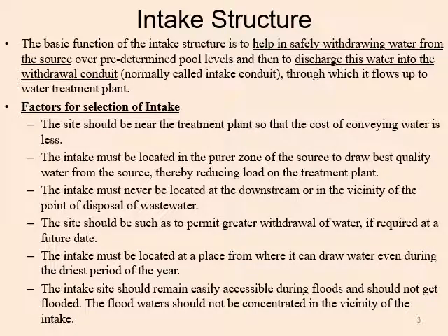The intake must never be located at the downstream or in the vicinity of the point of disposal of wastewater. So the structure should not be located at the downstream side towards where the water is flowing, or nearby the area where from any other source the wastewater is being disposed of.